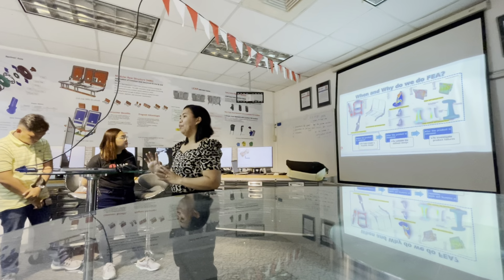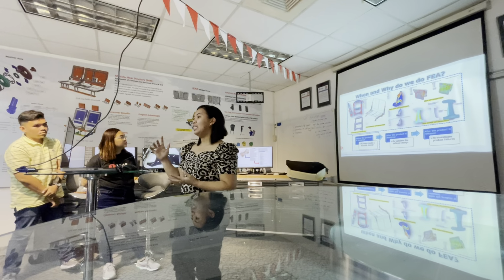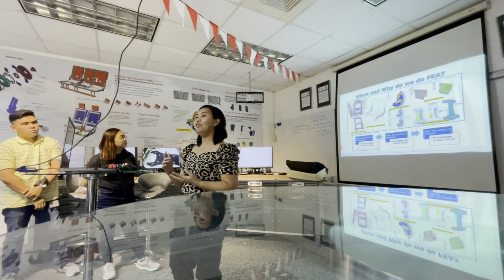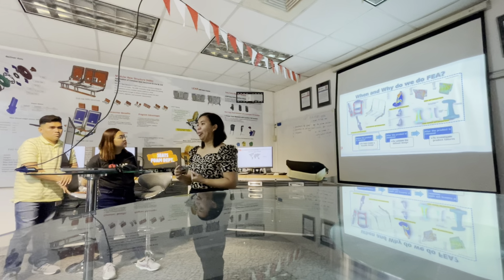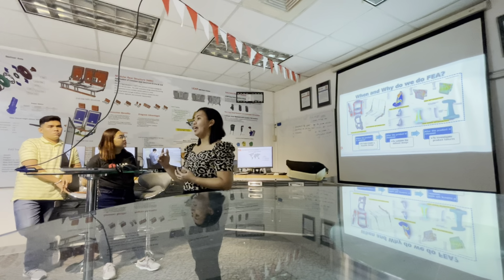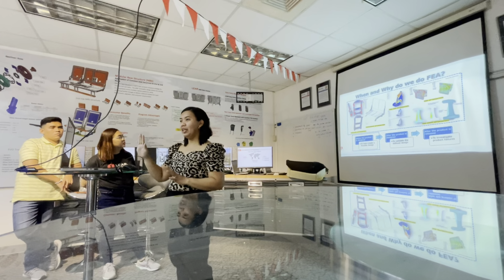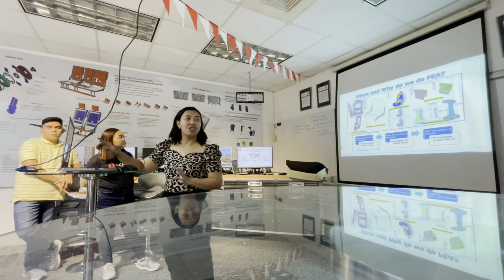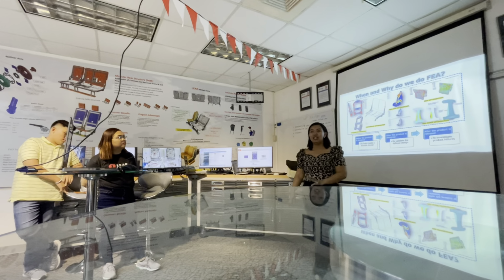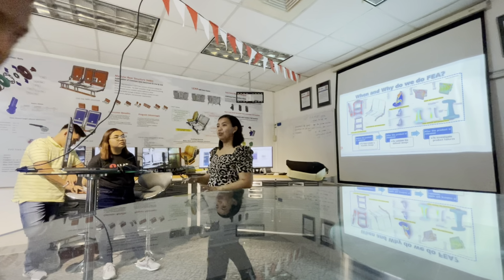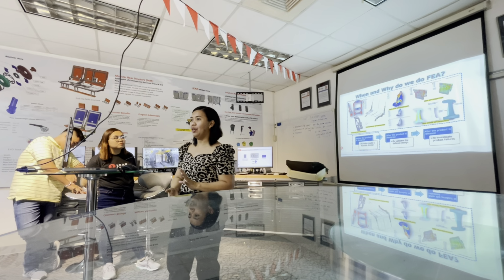So another type of optimization that we do is, we call this free size optimization. This is useful especially for composite materials because in this optimization, we are trying to find the optimum thickness distribution within a part. So imagine this is a carbon shell, this one. This is a carbon fiber shell or a glass fiber shell. So we are trying to find out what will be the optimum thickness distribution in the entire seat structure.